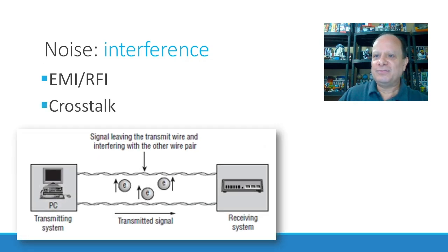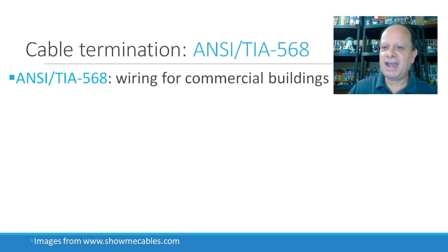When a pair is in use, an electric field is created around the cable. This electrical field induces voltage in adjacent pairs. With the transfer of the signal, the more parallel the conductors, the worse this effect is, and the higher the frequency, the more likely crosstalk will happen. Twisting the two conductors of a pair around each other cancels these electrical fields and minimizes the damage caused by crosstalk.